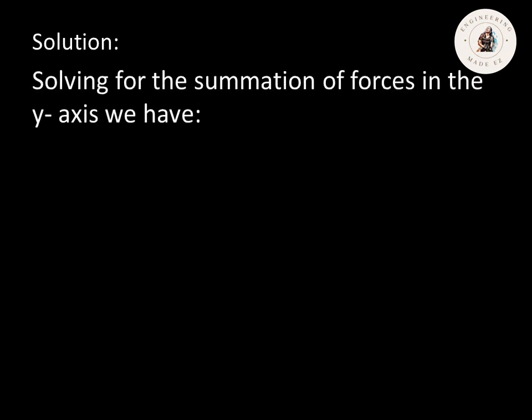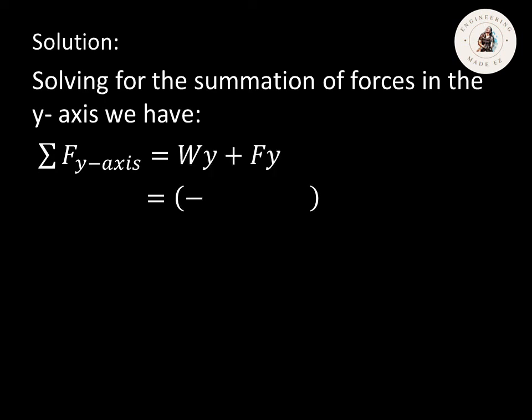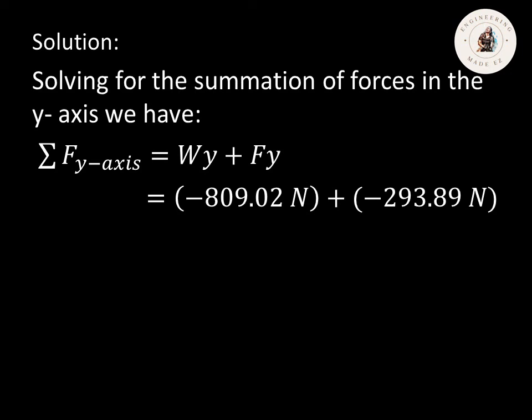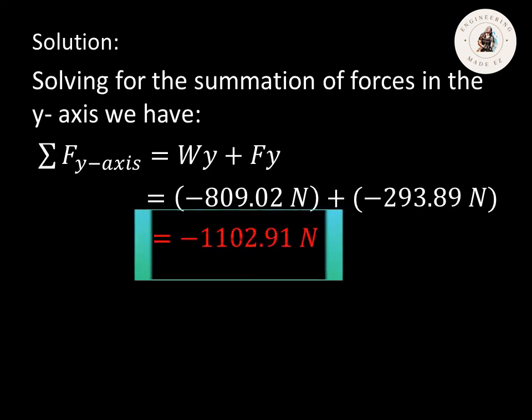Solving for the summation of forces in the y-axis, we have Wy plus Fy. Take note that based on our calculation a while ago, Wy is equivalent to negative 809.02 Newton and Fy is equivalent to negative 293.89 Newton. Adding them, we had an answer which is negative 1102.91 Newton.